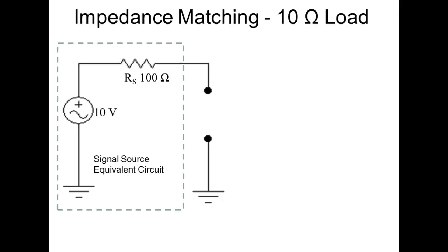If you don't believe me, go out there and, without cranking your car up, put a meter across your battery and turn on your lights. What will the voltage do across your car battery? It'll drop. Now remember, with your alternator, we have what we call a regulated power supply. We understand that now, right? So your alternator has a regulator on it. So if the output of the alternator drops down, they put more power into it. They make more power available.